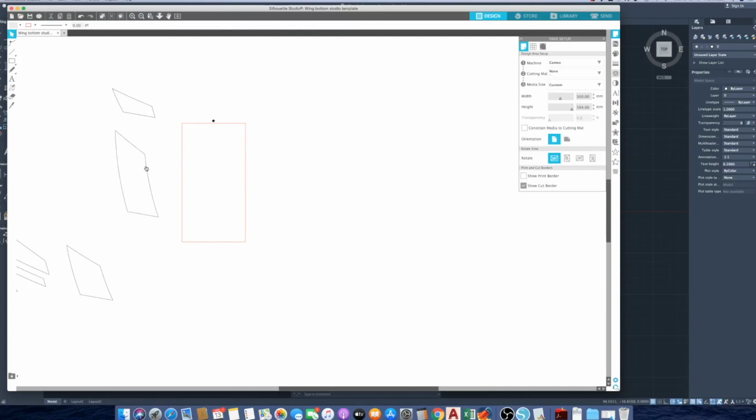You'll have to mirror them. So if you want a left and a right, you need to copy this part first. Copy and paste it, so we have two, and then just mirror it, flip horizontally. Now we have both left and right. And you can flip these around and reorder them in order to try to fit them on your piece of covering. These parts are big on the wing, so they're definitely going to take up more covering than the stab. The stab you can usually get a couple pieces on within that 12 inches.